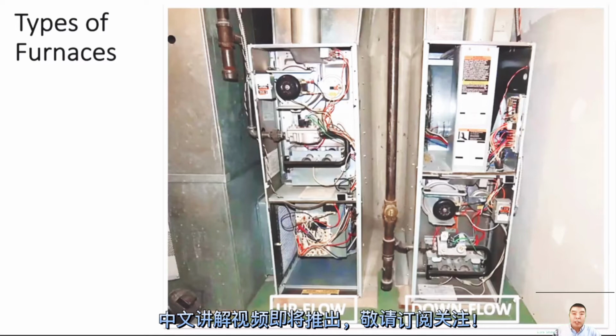All the information should be in the manufacturer's manual. So if you install it in a different orientation than upflow, you should read the manual to know how to change the inducer motor direction. So don't cause trouble for the condensate.